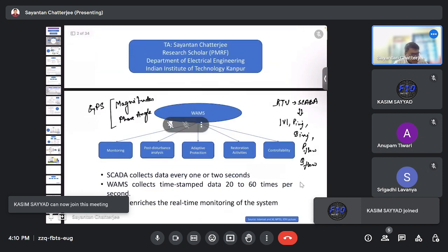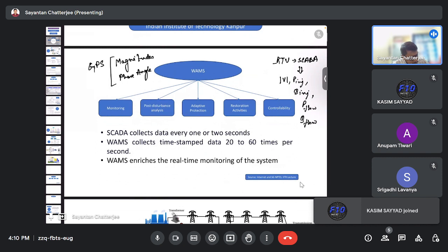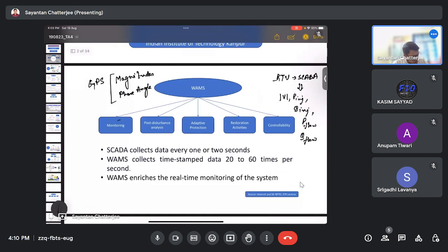Mainly we are looking to find out the magnitude and phase angles of the entire power system in operation. The advantage the PMUs and this wide area monitoring system give is that it directly allows us to measure the magnitudes and phase angles of the system. These two are the base states of the system.